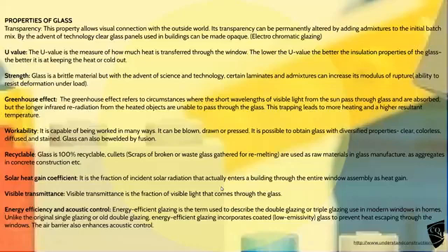Strength: by nature glass is brittle, but you can laminate it and you can put admixtures in, so you can get toughened glass by annealing, or you can get 2 or 3 or 4 sheets of glass laminated together with a plastic film, so they produce one sheet. If they do get hit and cracked, they stay together like your car windscreen. Again, YouTube's got loads of videos of idiots trying to smash the stuff.